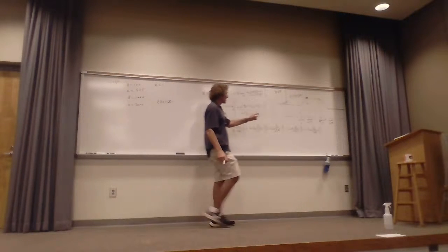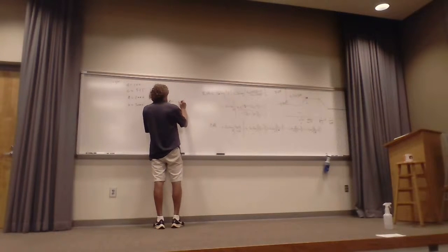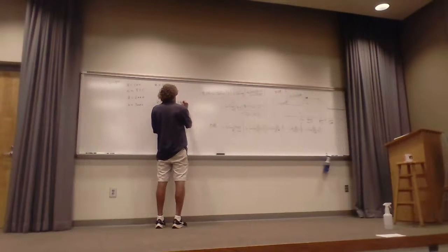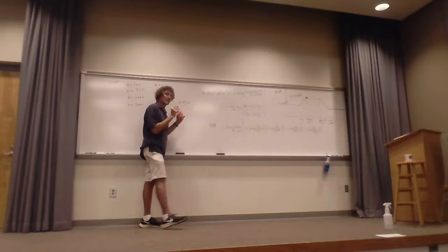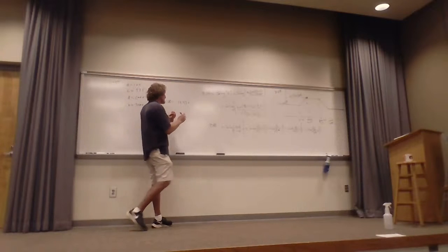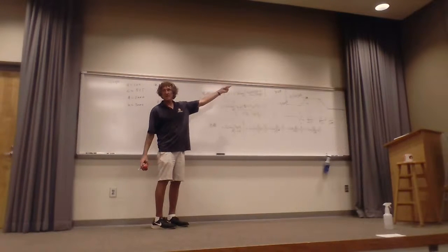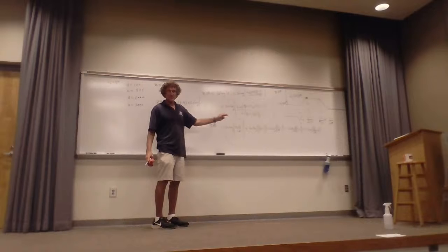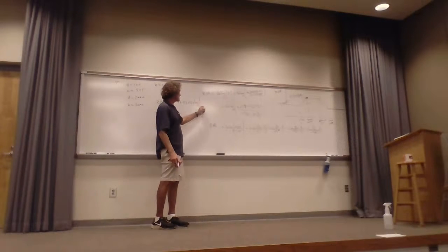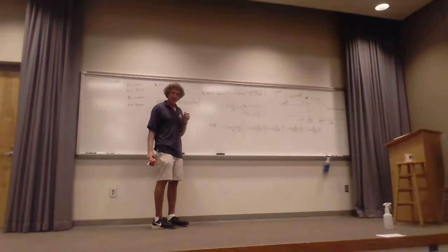Start with the value down here. Minus, please watch this, minus 17.93. Then it's going up 20 dB per decade, right? So the next thing you put down is 20 times the log of the ratio of the frequency it ends at divided by the frequency it starts at. Remember, if that ratio is a full decade, the log of 10 is 1, so you'd add just 20. Follow me on this?